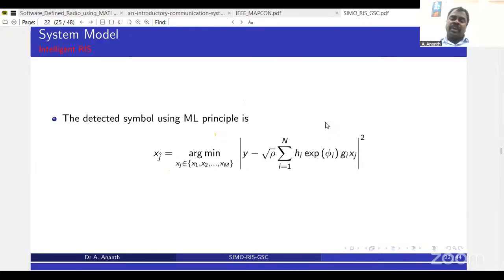So when you are transmitting a signal, you have a scattered point because of noise. What we do is, from that received signal point, we try to find out the distance with respect to +1 and the distance with respect to -1. Whichever distance is minimum, we decide in favor of that. That is what is called the distance-based detection metric, which is our maximum likelihood principle.